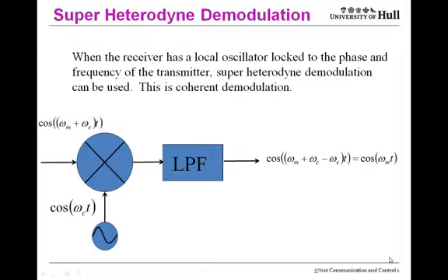So here we have a typical coherent demodulator based on the same superheterodyne multiplication process that we saw in the modulator earlier. At the input we have our modulated signal, which is our message signal that's been upshifted by our carrier frequency. When we mix that with our carrier frequency, at the output we have two components.